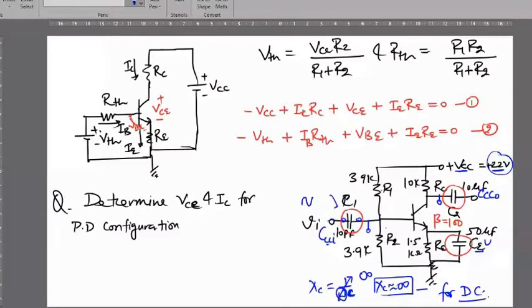Yes, sir. And this is called the emitter bypass capacitor. Sometimes there is heavy flow of current across the emitter resistance RE. If there is heavy current IE across the emitter terminal, which is a combination of input current as well as collector current, both coming from the supply, there is a chance of burning out the transistor. In bigger systems, we cannot afford this.